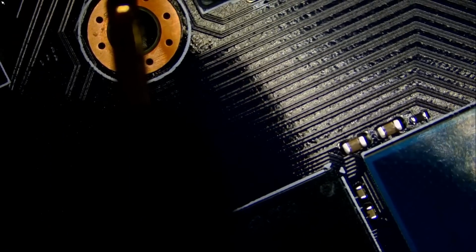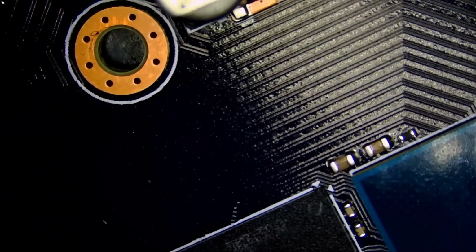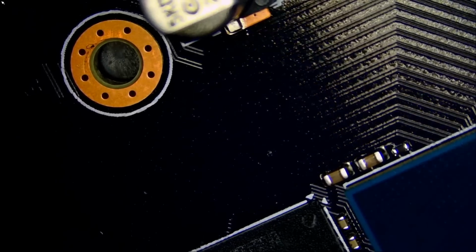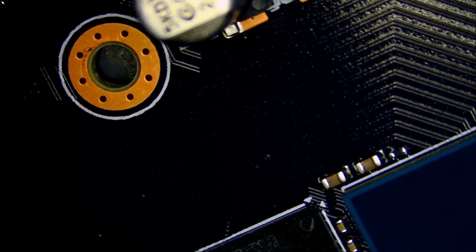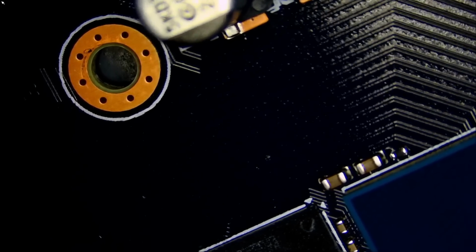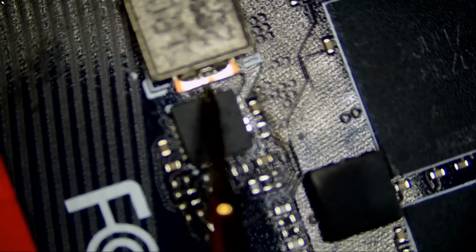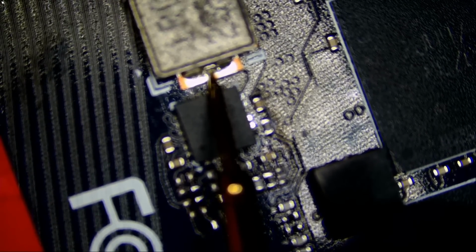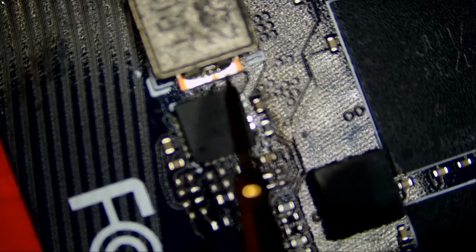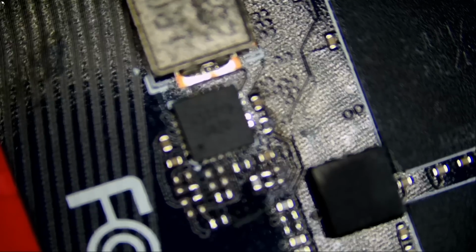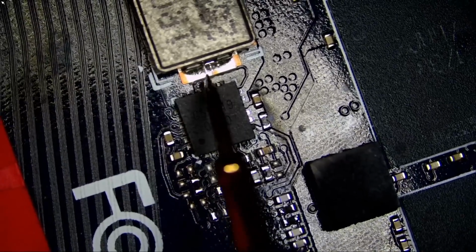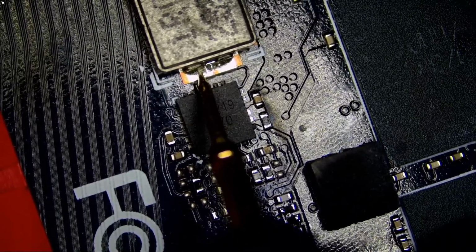Something strange is going on. We do have 0.9 volts. Our PCIe voltage 12, we do have it. And our 1.8, I'm reading 1.214. Wow. We have 1.2 volts right under the memory chips. Right here. That's supposed to be 1.8, right? I mean, we did measure it in ohms mode, and we got a 250 ohm reading. Sounds like the 1.8 volt line. What is 1.2?